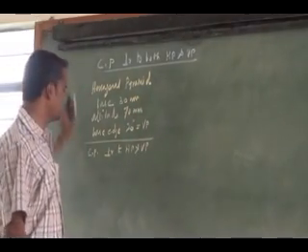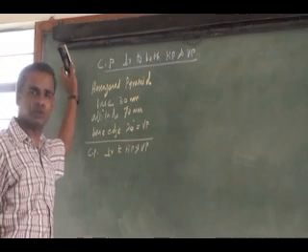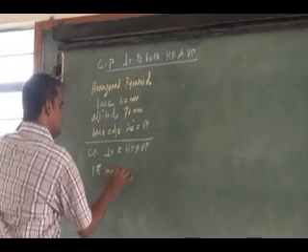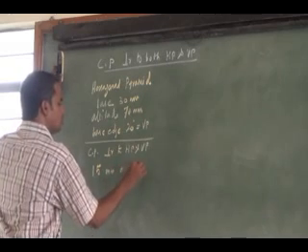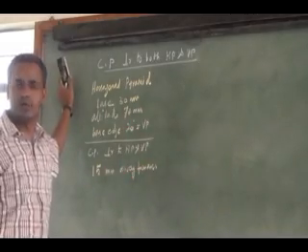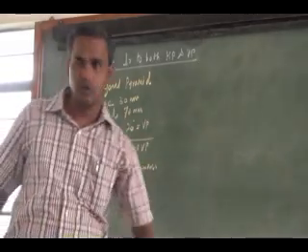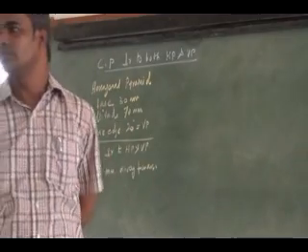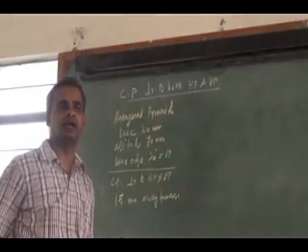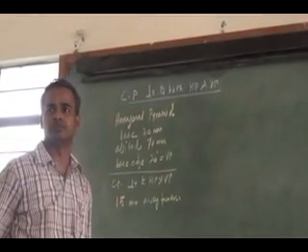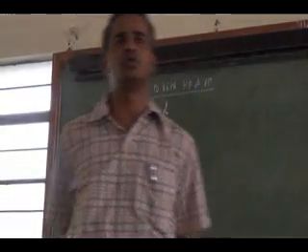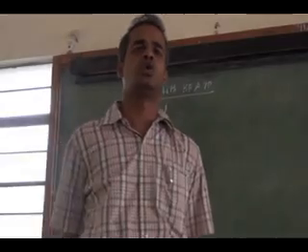The solid is cut by a plane perpendicular to HP and VP, 15 mm away from the axis. Right. Full stop. Draw the front view, top view, and sectional side view. Which of these views will hold my true shape of section?